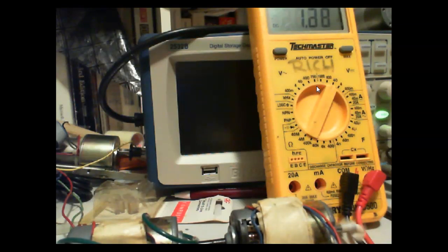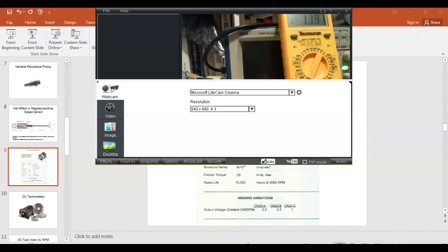Right? So what's a closed loop system? It's also called a servo system. What are these systems? They give feedback. Closed loop gives feedback, but open loop is at a set point. What it does is it looks at the feedback, and if the feedback doesn't match, then it does something to the output to try to cause the feedback to match, right?